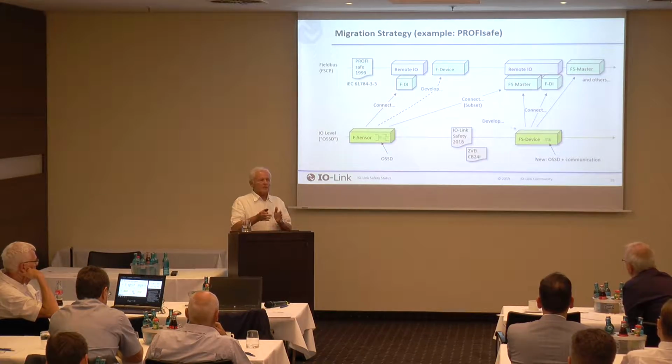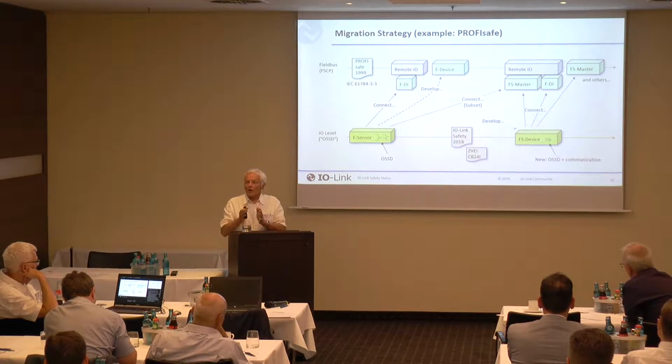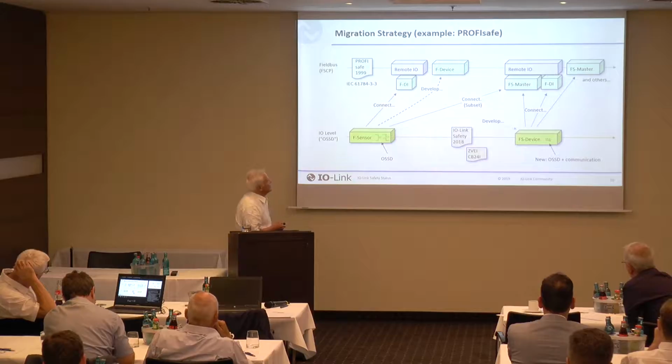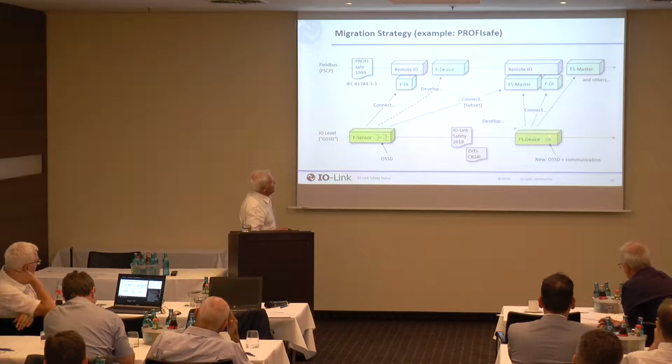An FS Master can be built with OSSD support or not. This is an option. It depends on the manufacturer of the safety master, of the FS master, whether it supports OSSD or not. The safety sensor manufacturer can develop a new device supporting OSSD like before.